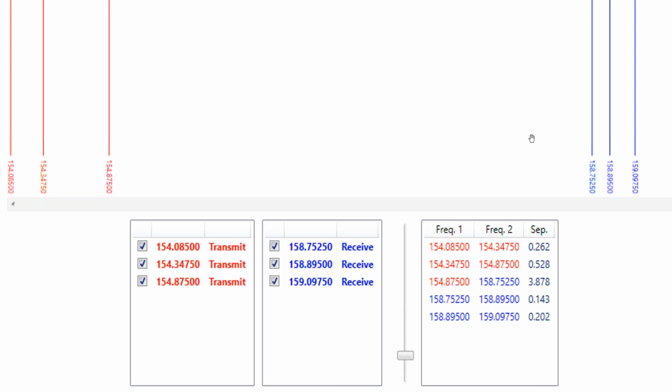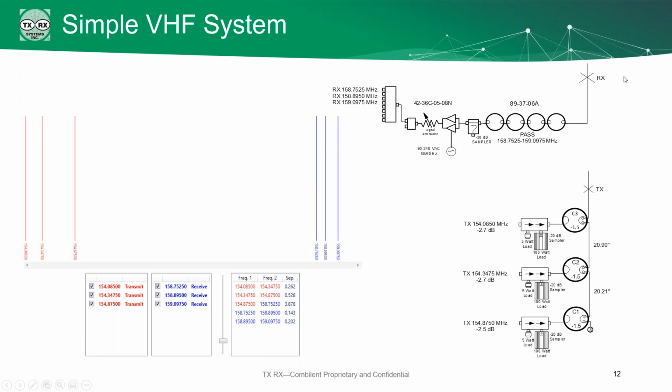With such a wide guard band, it's very easy to achieve the isolation required, which is accomplished with just three TPS cavities per channel. The TPS cavity does the job of both combining the three frequencies as well as providing the necessary filtering on the TX channel. The receiver side is also relatively simple, just one bandpass filter consisting of four 4-inch bandpass cavities. The reason we need the 4 cavities is to achieve a wide enough bandwidth to cover all the RX frequencies.